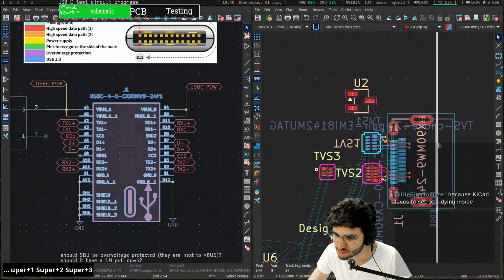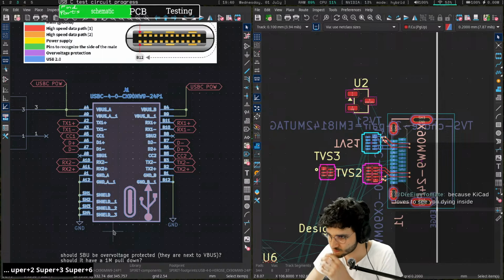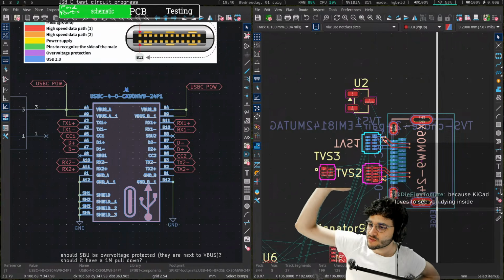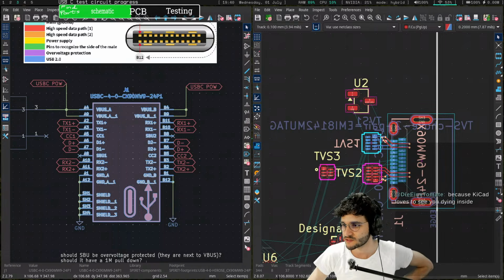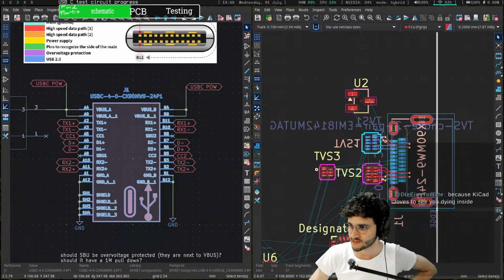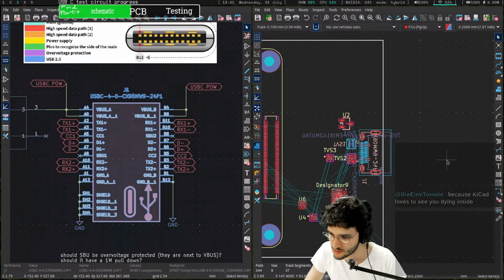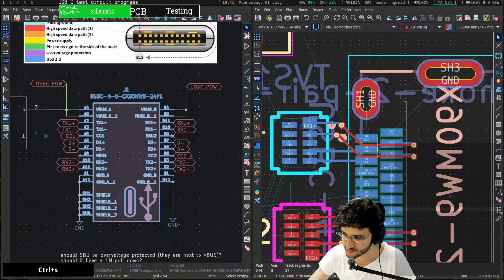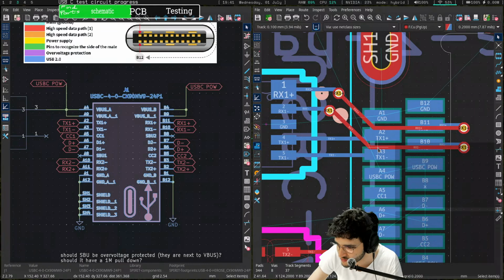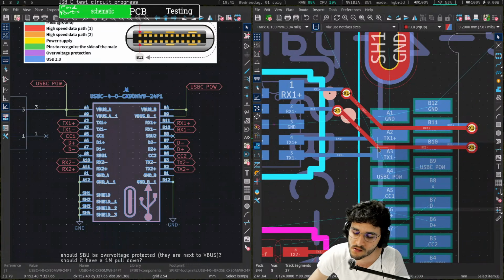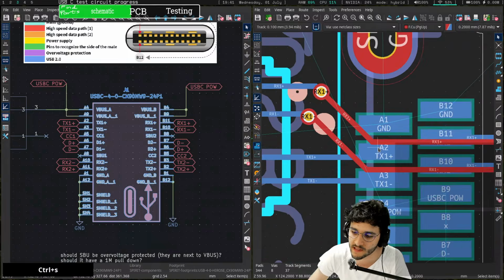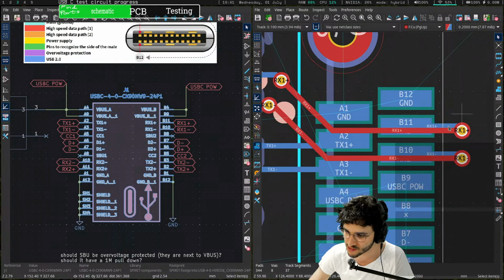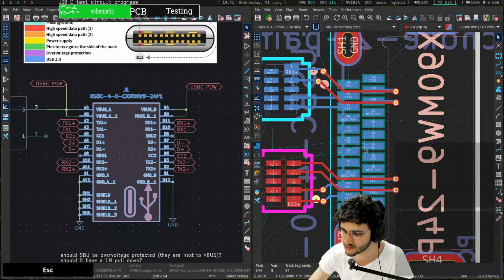Alrighty. I have only ever used EasyEDA, so I don't understand why you can't just draw traces in any shape you desire. Well, these are kind of special because they are high speed signals. So I'm trying to make them symmetrical. And I'm also trying to leave space for the future stuff that I have to connect around here. Like the power, the D1, the blah, blah, blah.